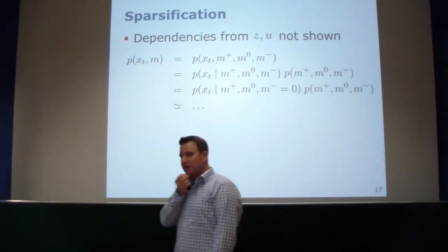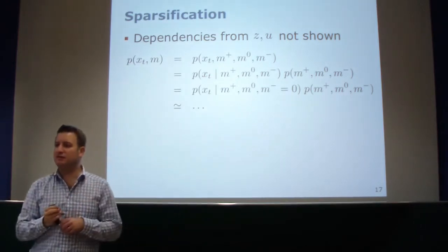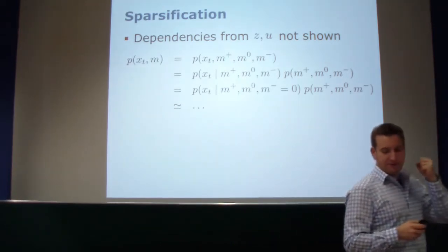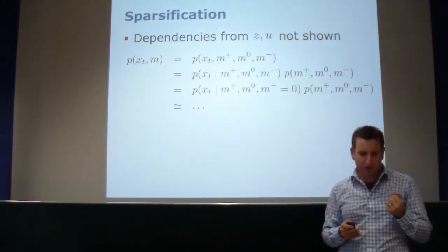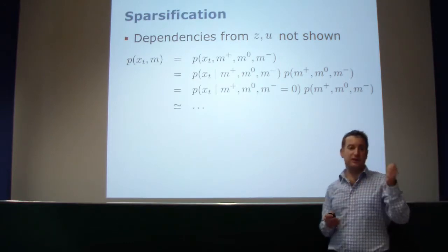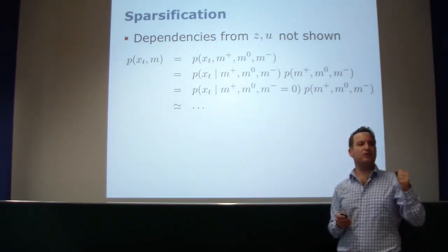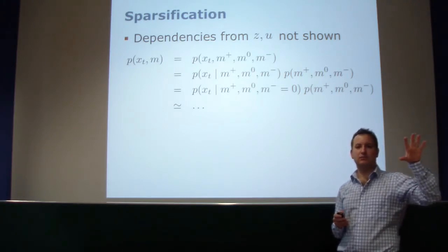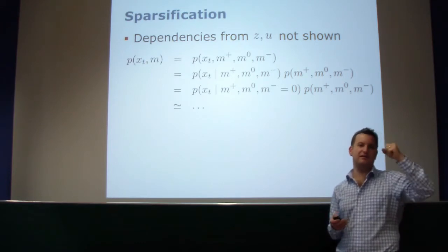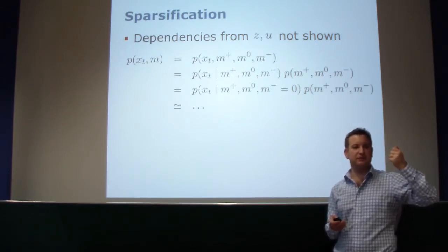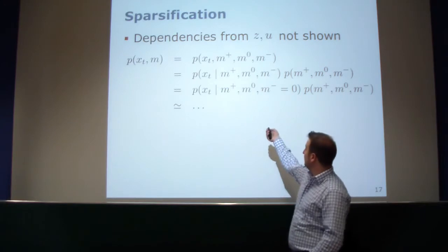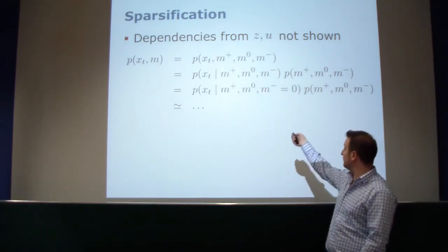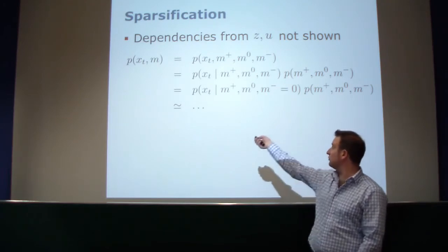Now in the SEIF formulation, because I have my active landmarks, the passive landmarks do not contribute to the estimate of the robot's pose, given I have my set of active landmarks. Of course, the update step in the SEIF only depends on the active features. So I can simply set them to 0. So we ignore them. I just set them to a value 0 because their values don't contribute to xt.